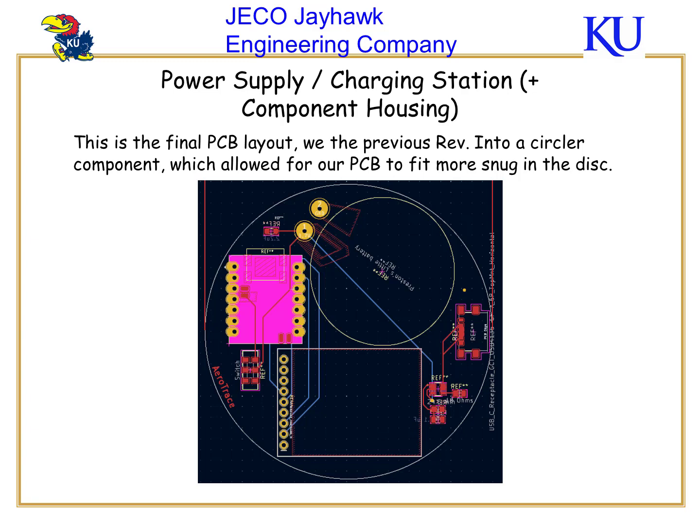To explain the PCB, in the bottom left part of the circle is the USB-C input, which has a voltage rating of 5 volts DC. This gets put into the charging controller, from which a current is set using ISET from the charging controller's datasheet. In our case, we had an RSET value of 2.1 kiloohms, which produced an ISET value of approximately 214 milliamps.